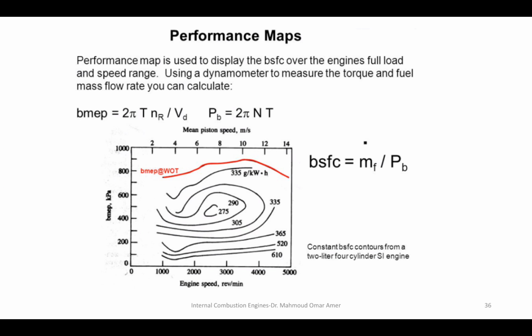What happens to the power with RPM? It increases as you increase the RPM till you reach a limit, then it drops again. Check this line, you see that it increases, then it drops again. This line also, neglecting the first part, which is for other cases. It increases and drops, again and again.